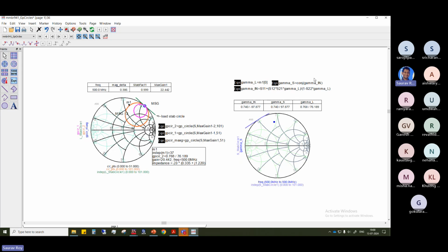So how do we do that? For that we have another calculation here. Using the Smith chart, as you know, here you see 0. It shows what is the impedance value here. That is gamma L at this point. If you define a marker, this marker value M1 is the load resistance. It gives you the gamma value, gamma L. You understand that, right? And the same thing is shown here also. So the first thing, the marker M1, is the gamma load value.